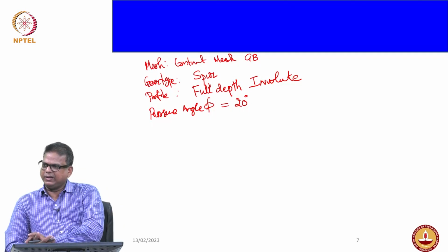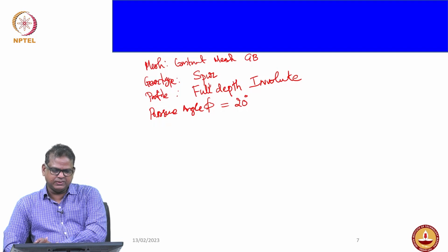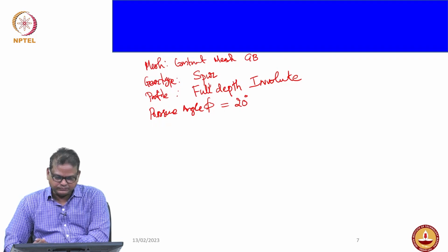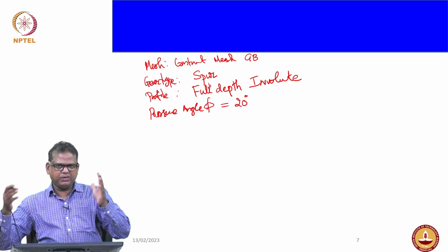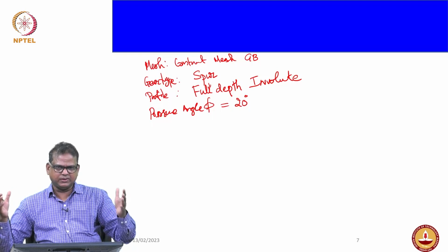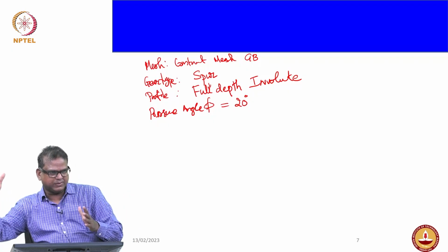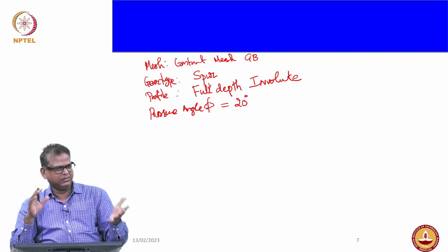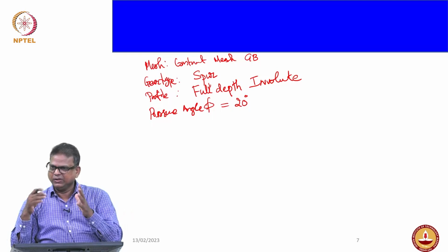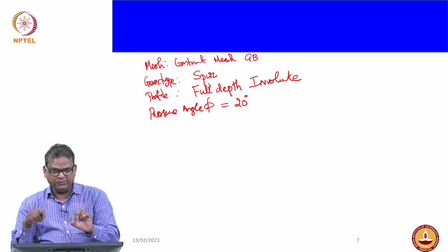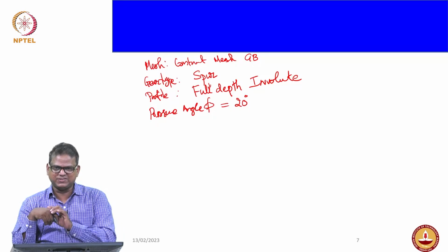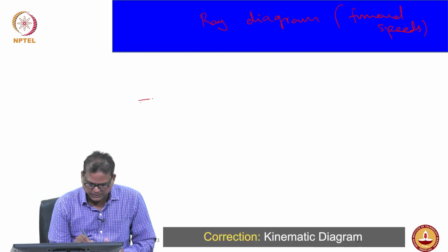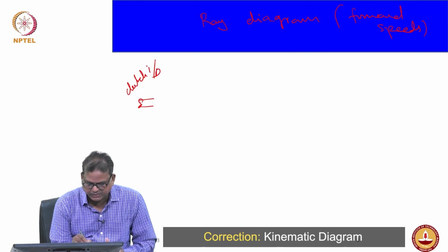Another piece of information I would like to emphasize. The constant mesh is fine. How are we going to arrange the gearbox? Can we arrange the speeds from right to left or left to right? Either way is fine. But after doing that, you have to check the dynamics of the rotating masses. That is very critical. So first you would expect the shaft from the clutch input, right? The input is coming from the clutch.